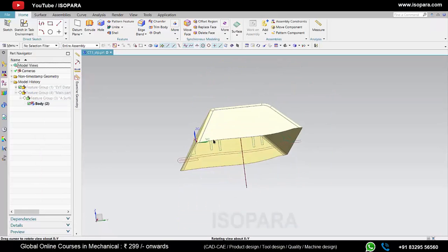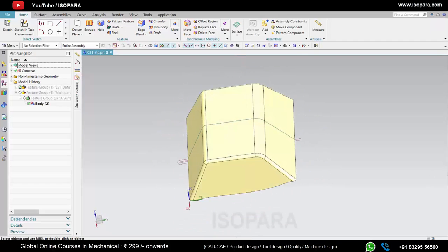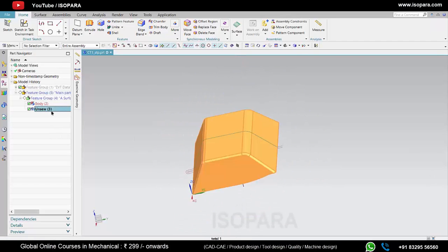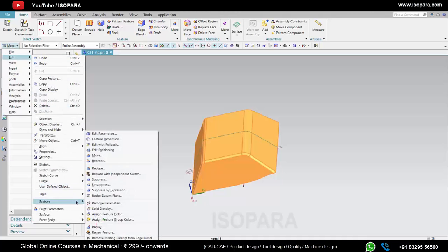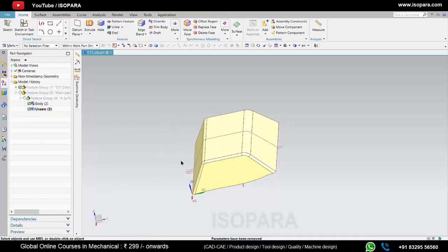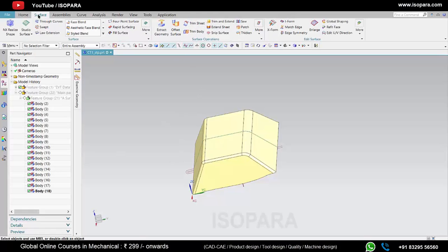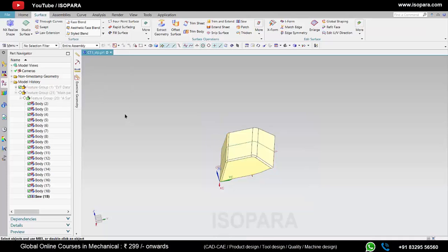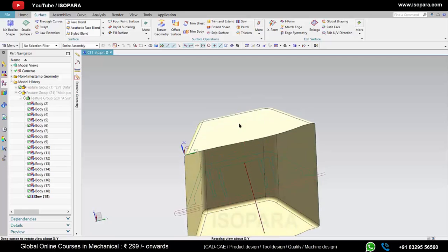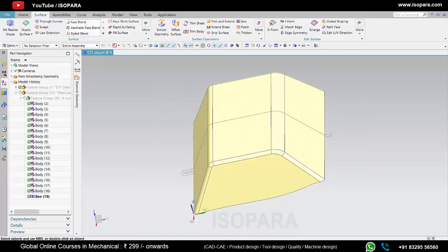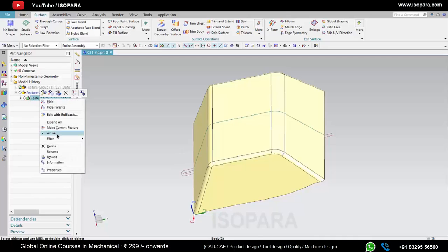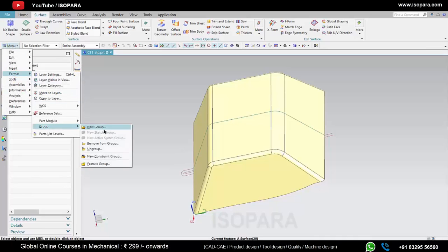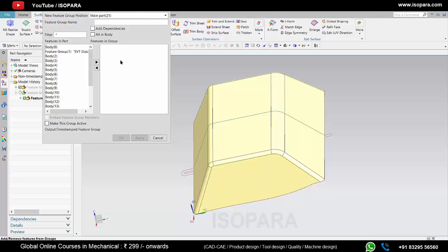Okay, so here we have the body, and I moved it to the A surface here. So unsewing and removing all the parameters will create one body for each face, and then we can sew them up within our tolerance limit to get all the continuity and a smooth surface. Now the B surface.